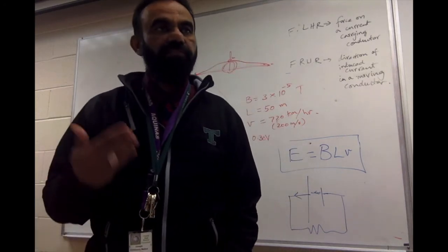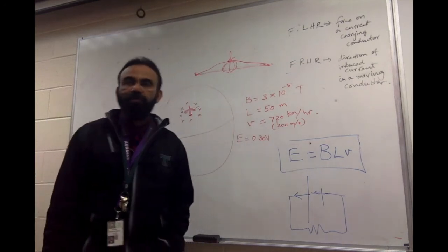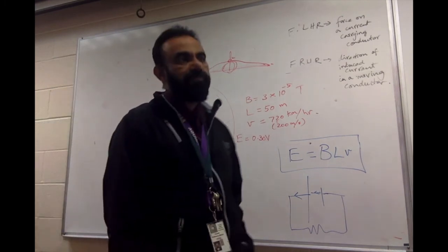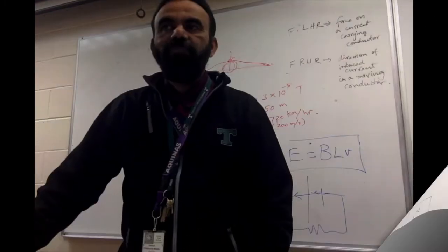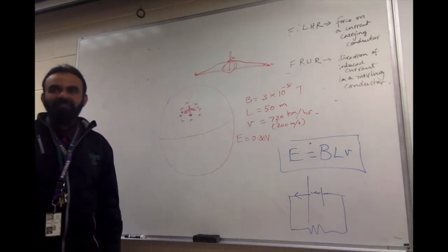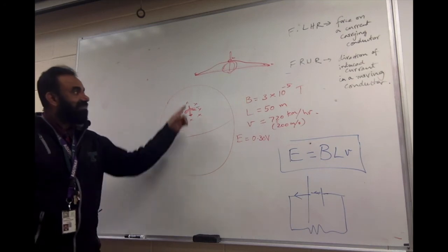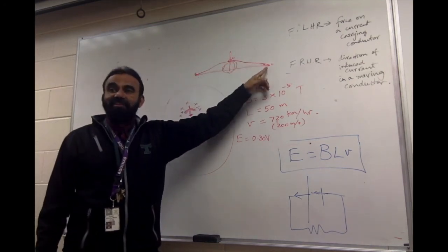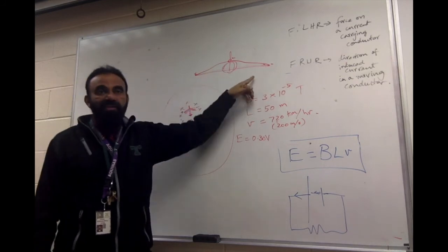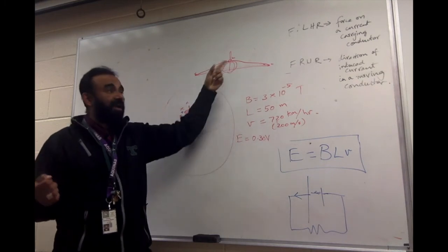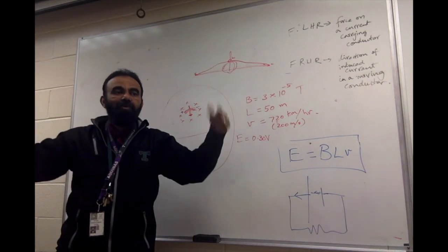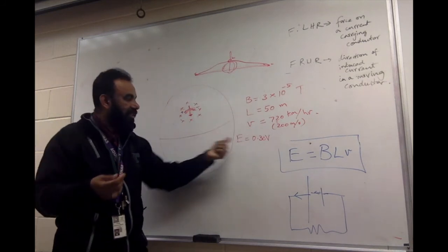If yes, answer. If no, reason is more important. Will that light bulb glow? Think about it. No, because the wire is also a conductor. That's the answer. This wire is also another conductor cutting flux lines once again. So just as the wing is establishing 0.3 volts, the wire is also a different conductor, also cutting lines, and therefore will induce 0.3 volts.